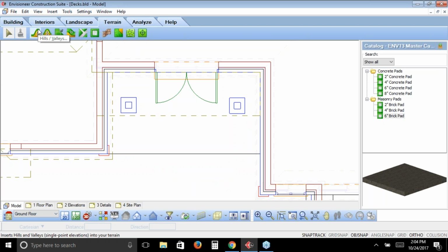So you can modify the shape of the existing pad that you put in those 2 different methods. Stretching out an entire edge by hovering your cursor over the solid blue squares on the edges that appear. And as you hold down your left mouse button, you can stretch them away. Or putting your cursor over top of one of the clear corner grip points, and by holding down my left mouse button and bringing it to a new point, I'm stretching just that one corner away.